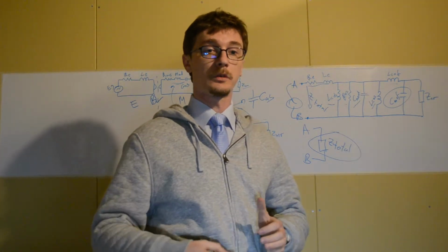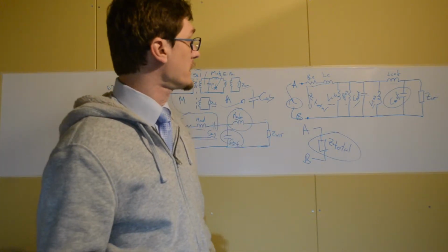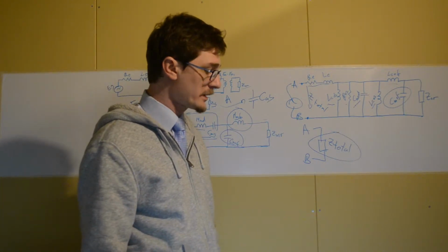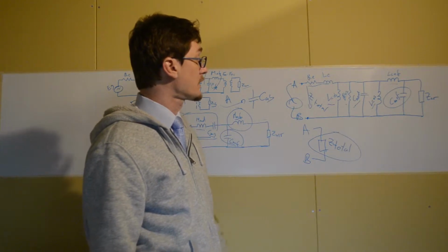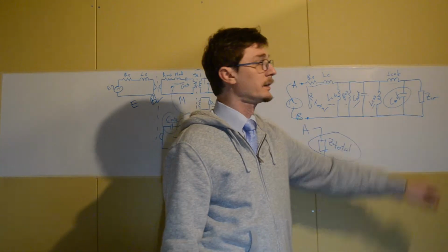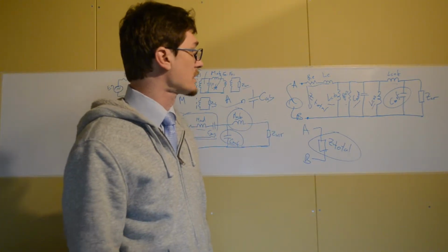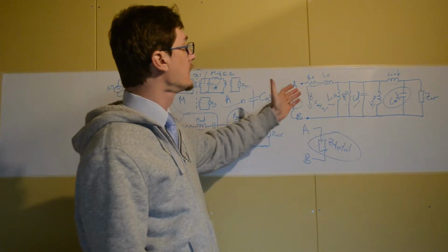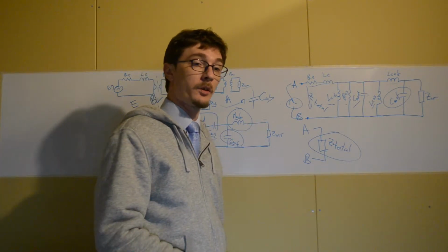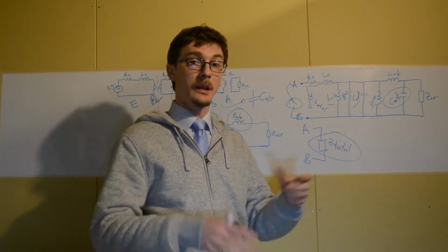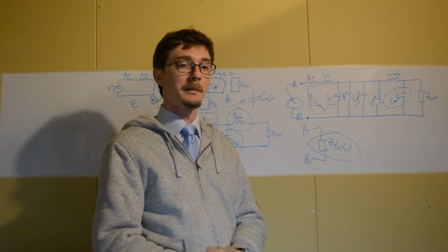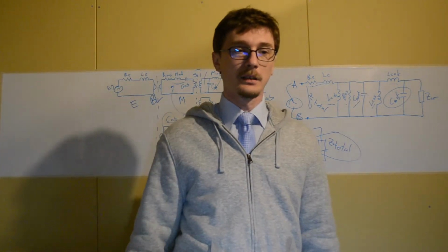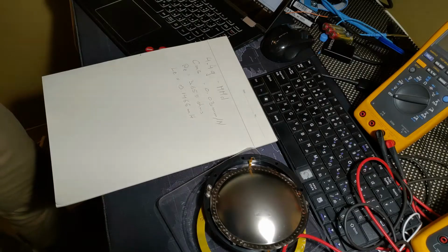Again, it's free software that you can actually script and calculate and vary all sorts of parameters. I like that more as opposed to Spice, because with Spice it's going to be very difficult to simulate components that vary with frequency. They usually use lumped components, but if you do it analytically, and basically put that formula into computational software, then you can vary parameters within that formula, and you get a better result, in the sense that you can try more things and see how it affects the impedance and all that. So let's go to the computer and try it out.